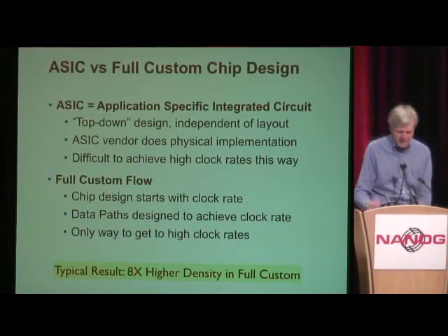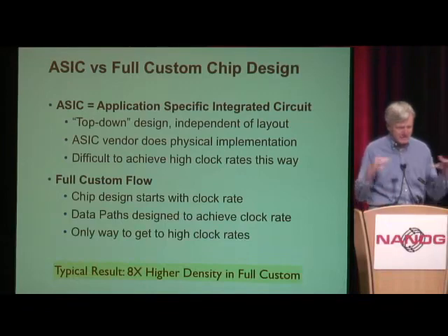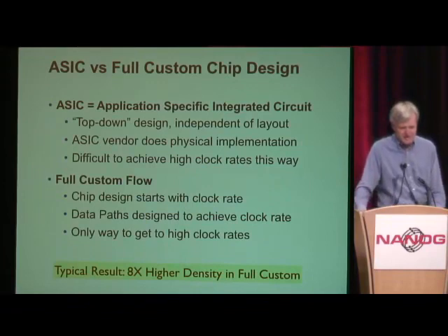But there is one other problem here, which is the way most networking chips have been designed in the past is the so-called ASIC flow. ASIC stands for Application-Specific Integrated Circuit, which means that the system vendor designs in Verilog the high-level logic, and then throws this netlist over the fence to the ASIC chip vendor, who actually then does the physical routing and placement on the chip and brings the chip back to the system vendor.